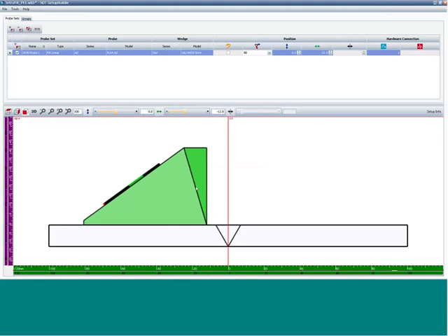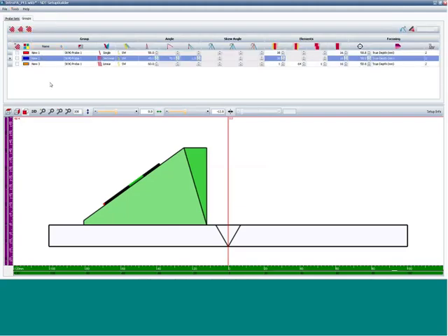After we have configured the component, the probe, and the wedge, primarily from database entries, now we can move to the beam formation. A group defined in the OmniScan is a group of focal laws, or A-scans, that share a common skew and channel within the instrument.